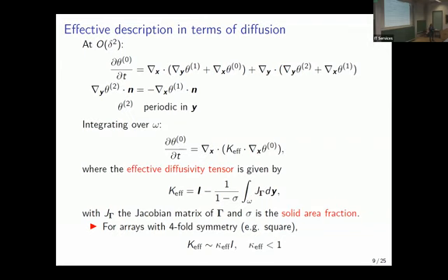This is not so obvious at first because you put obstacles, and these obstacles occupy some area, so that enhances dispersion because the scalar doesn't have to go very far, doesn't have to discover so much of the area to disperse. But at the same time, you have a reduction of the scalar flux on the obstacles, and this leads to the inhibition of basically the dispersion. So the second mechanism wins, and it turns out that the effective diffusivity is less than 1 always.